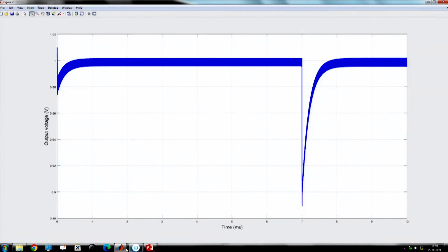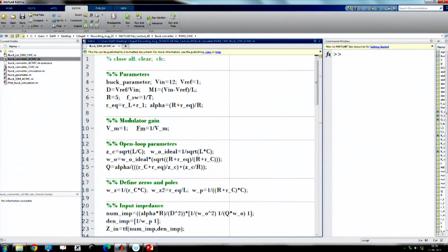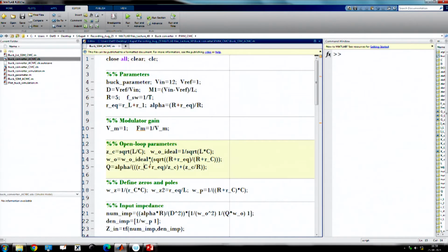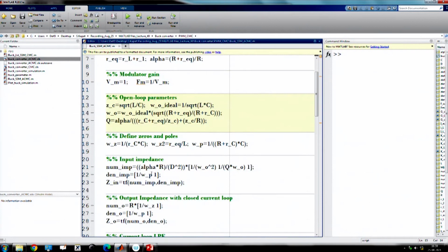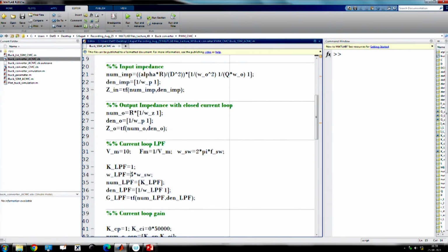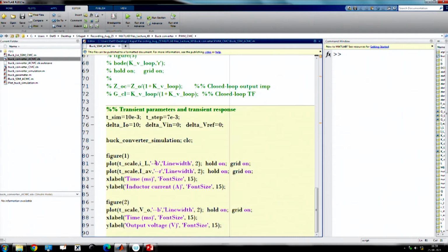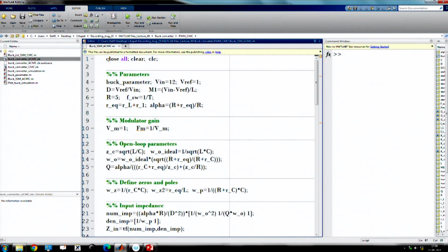Now, we want to repeat this experiment, that means we keep, because instead of putting multiple waveforms, we want to run it here, the same waveform. Now, it is the dotted line, okay, and now we want to further reduce the current loop low pass filter bandwidth to, let us say, 2 times. Now we are using solid line. And we want to plot one over other.